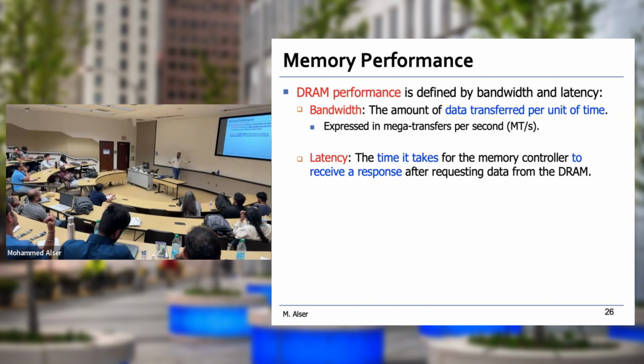How do we make the latency higher? By accessing different rows. We access the first row. We now pre-charge it, closing the row. Now we want to activate another row, right? So we want to bring it to the sense amplifier, read it, send it to the data bus, and then pre-charge again. That latency is different than the previous scenario. The previous one was shorter because we didn't do a pre-charge for every request. We are reading the exact same row, but different columns.